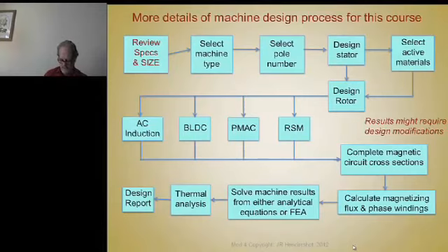There's software to do that, but you can use lumped parameter methods for that, which have been used for many years. But all of those thermal methods have to be backed up by some sort of test validation. What I mean by that is to do some analysis of some motors that you have some thermal data on, then use that to calibrate your model to use on the next one that hasn't been tested yet.